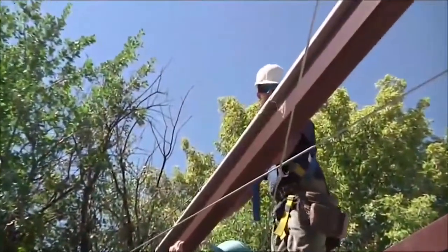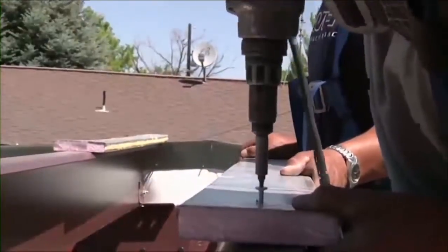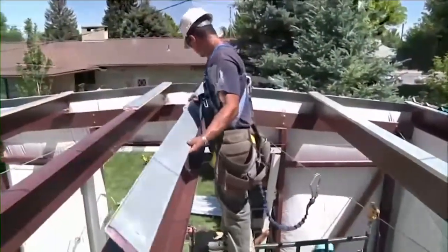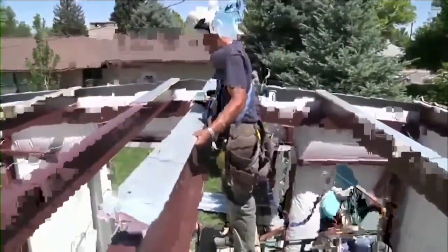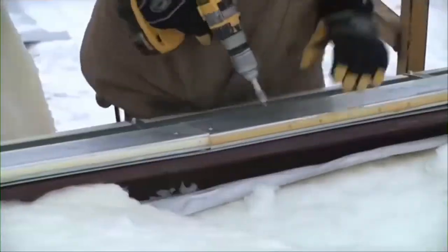When installing the thermal blocks, there needs to be an inch overlap on each side of the purlin to meet the energy codes. Each thermal block needs to be butted up to each other. Consider the placement of the flathead screws through the thermal block so that the sealed and safe fasteners are not in conflict with the flathead screws. Thermal blocks are placed over the tops of the purlins and are attached by 2 flathead screws. You can either screw the first flathead screw at the end and the second screw around 12 inches from the first, or you can screw the flathead screw at each end.